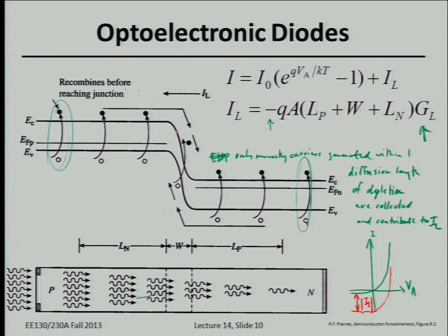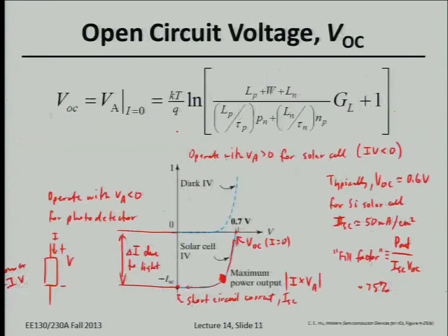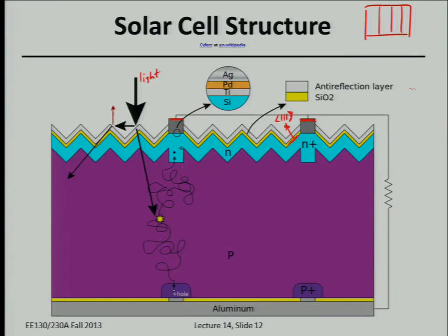So my question is a general question: if you were to stack solar cells, like layer 1, layer 2, layer 3, these all have different band gaps, and here's the direction of light shining in. Which material, which solar cell would you actually shine light on first? That means up here versus down here. Largest band gap first, that's correct.